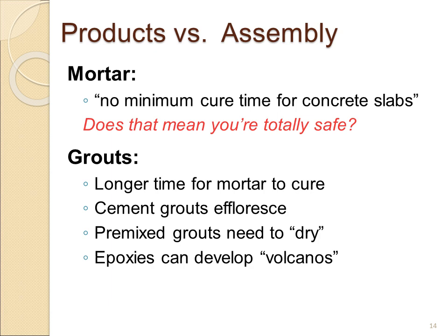And occasionally we see this condition where epoxy grouts are used, and because of the moisture vapor underneath these large format tiles, and now you have an impervious epoxy that's placed over those joints, the air pushes the epoxy during its cure time, just pushes the grout up, and you get these volcanoes that happen afterward.